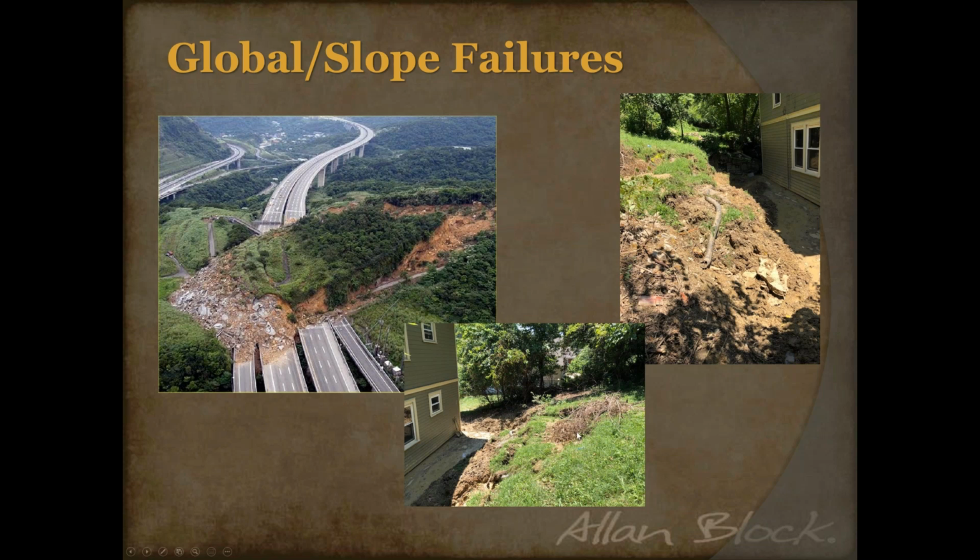I knew an engineer that I helped design a wall. He had a 3 foot tall wall with a small slope above. So I thought, oh, this should be no problem. But he also had a tall residential apartment complex above that wall, really close to it. And when I ran a global analysis, his standard wall, the small little 3 foot wall, did not pass global stability. So it could be a whole range of large or small walls. So always pay attention to what's happening on your site and what could lead towards a global.